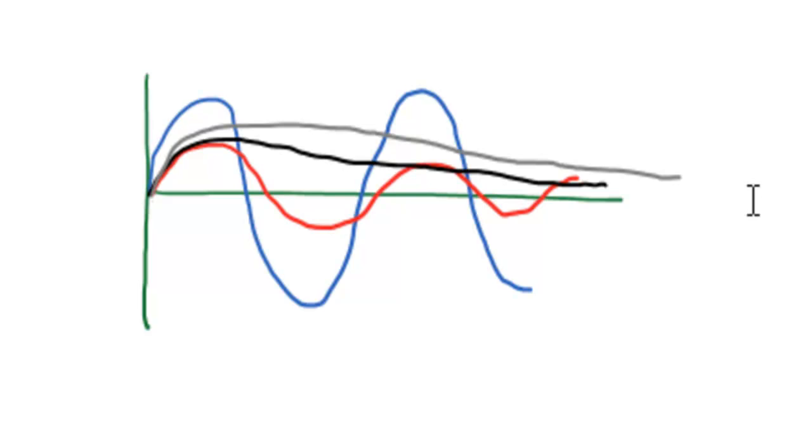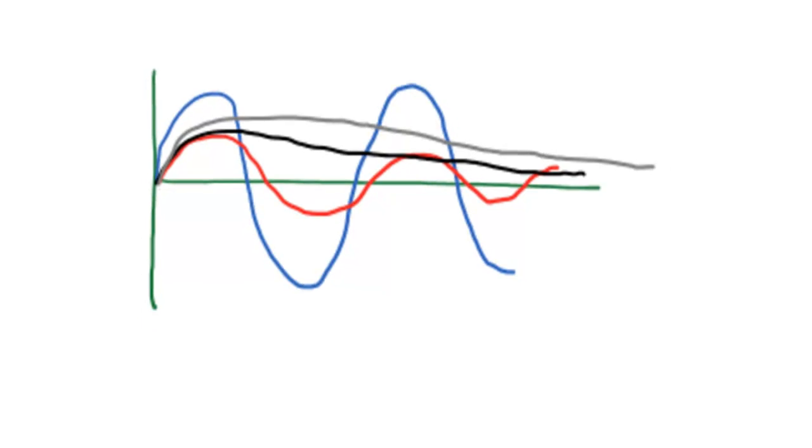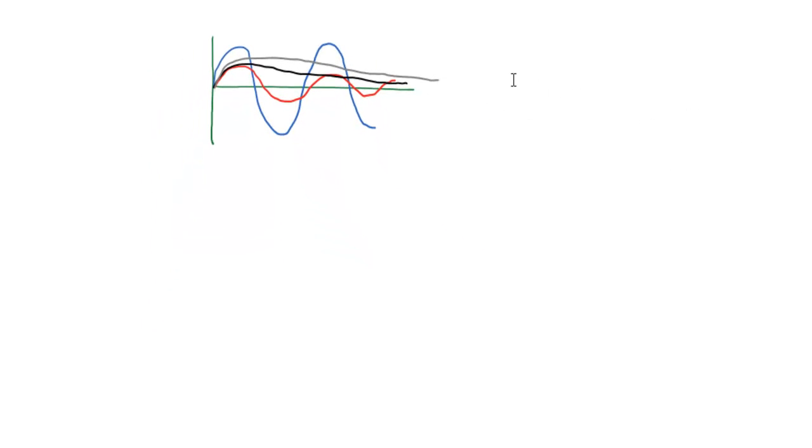But in general, you never see an undamped system practically. So we can conclude that to turn off the thyristor in class A commutation effectively, the load must be an underdamped load.